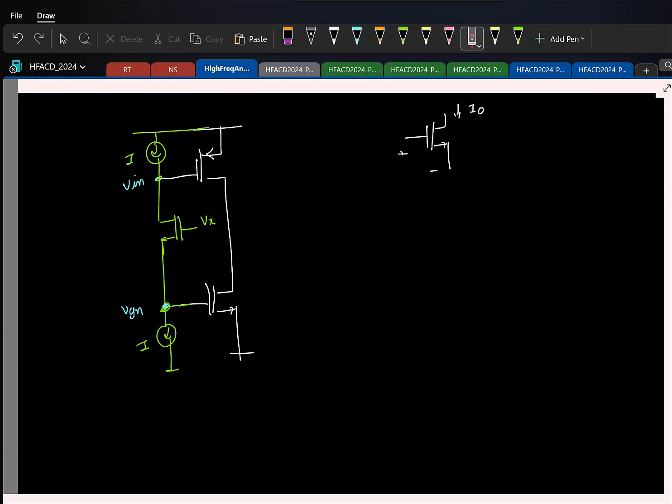But here if you see what's happening in small signals, so if I draw the small signal alone, I have, let us say this is some MA, I have the transistor MA here, gate is incrementally short, drain is where I have the small signal input V in, right?